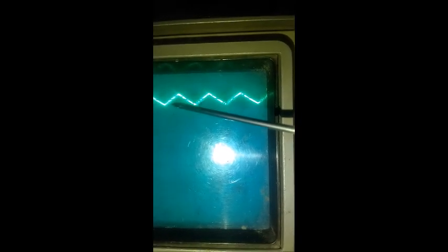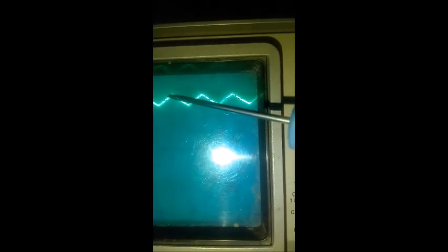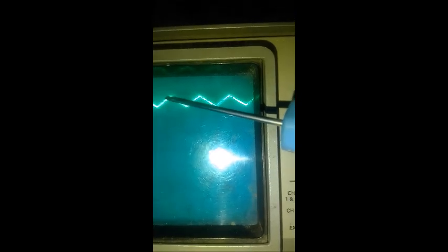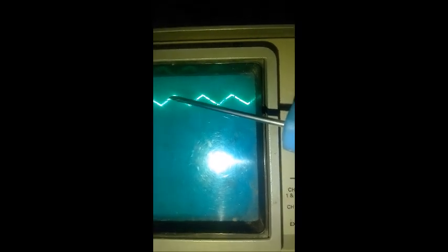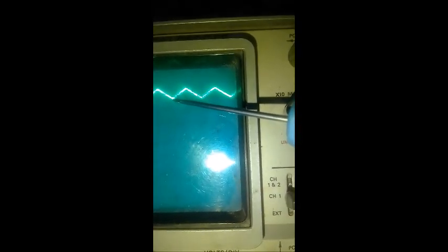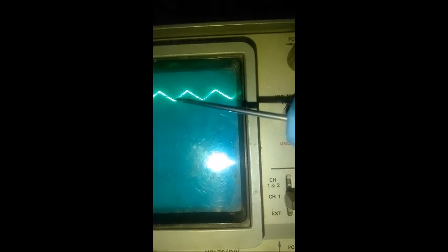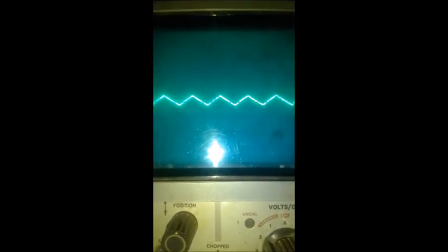The NAND gate, because it's a Schmitt trigger, charges by 1 volt and says the input is now high, then starts to switch and the output goes low. Then it starts to discharge and goes down by 1 volt. It says now the input is low, it switches to a high output, and that's the oscillation.